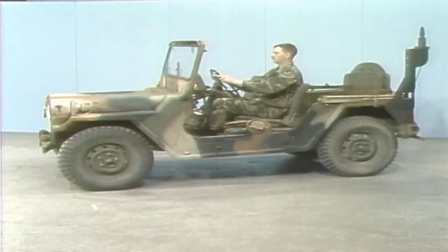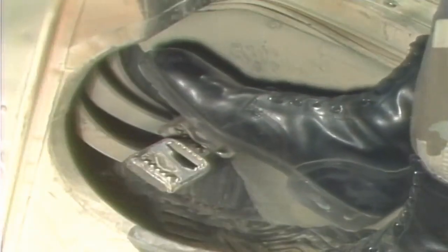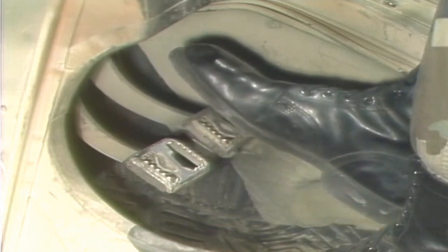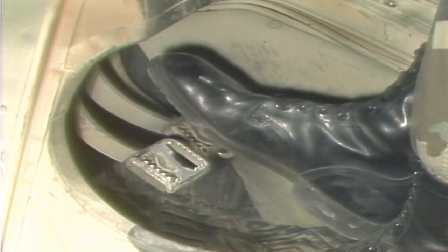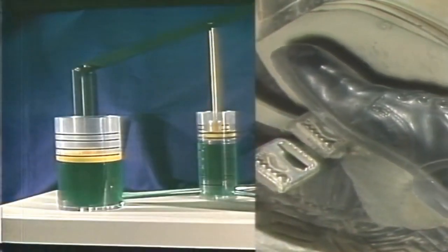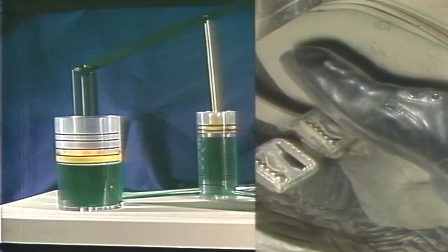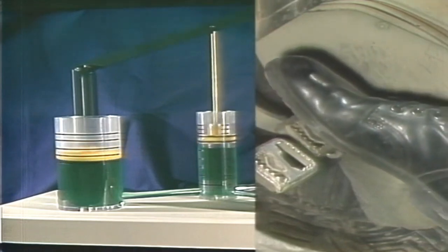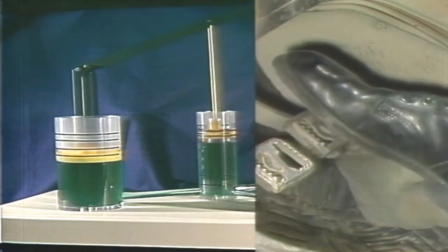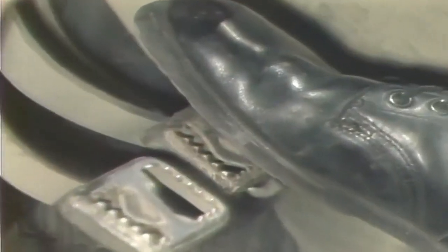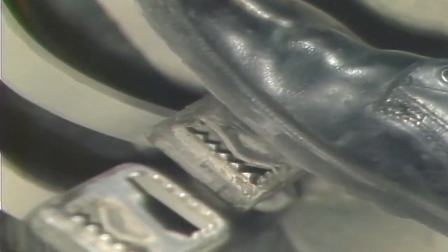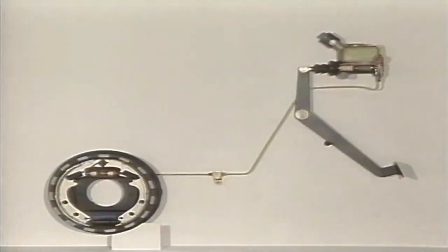Now we're ready to look at the entire drum brake system and see how it operates. You can control the amount of braking power the hydraulic system will deliver, all the way from slowing down wheel roll to wheel lock, by the amount of pressure you put on the brake pedal. Here's how it works. Remember that the brake pedal acts on the master cylinder piston, the same way the lever acted on the piston in our hydraulic system demonstration a while back. The brake fluid is not compressible, so the further the lever pushes the piston, the further the fluid pushes the second piston. The same thing happens in the drum brake system. The result is that as pressure on the brake pedal increases, so does the pressure exerted on the brake shoes by the wheel cylinder pistons.